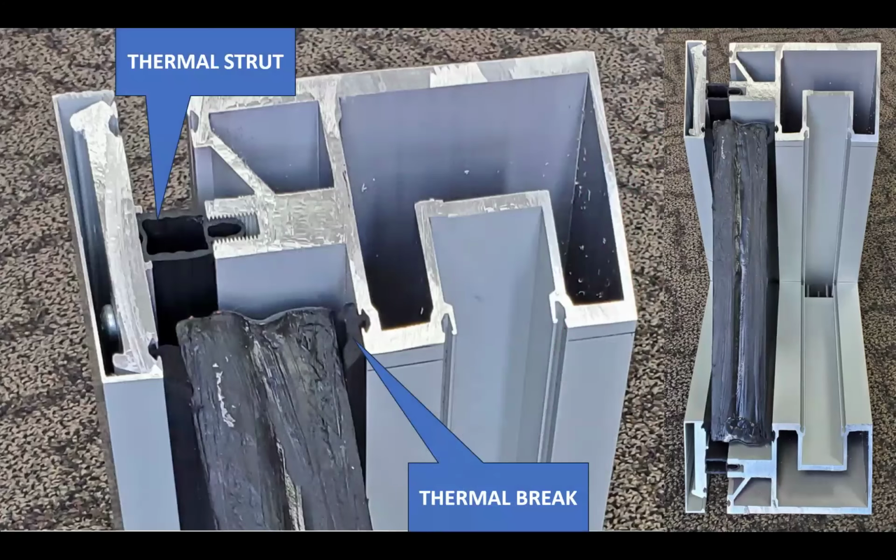But you have the ability to custom create, custom design, and incorporate thermal resistance into the exterior fenestration solutions as well with struts, thermal breaks, isolator materials. You can get thermally broken or thermally insulated, ballistic rated and blast rated glass clad polycarbonate glass as well that incorporates solar control or in some cases animal friendly applications as well. So if anything, you have now created this multifunctional fenestration solution and openings for the exterior envelopes or in some cases the interior aspects as well.